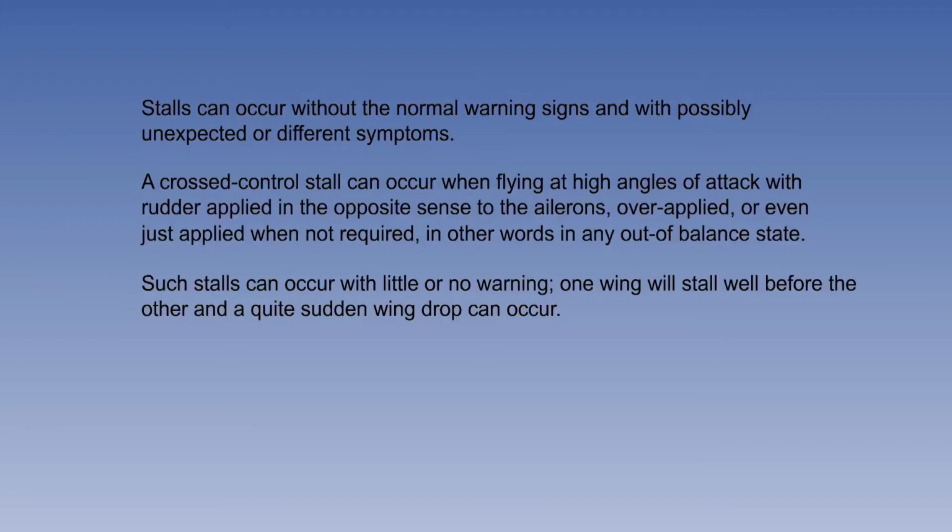The instinctive reaction to correct the wing drop with aileron must be resisted, as it could make the asymmetry of lift worse. At all times, and especially at low airspeeds in combination with high angles of attack, the rudder should be used to keep the ball in the middle to maintain balanced, coordinated flight.